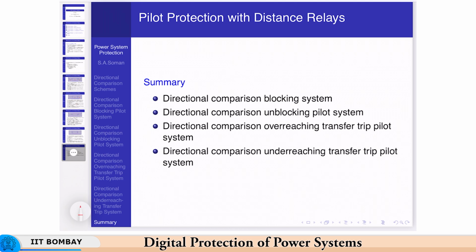another important topic, rather not a part of distance relaying. This is a feature which affects distance relaying, and that is how a distance relay sees a power swing. One reason why we discussed pilot protection before power swings is that though the pilot wire schemes will speed up the distance relaying decision, it will still not cover some faults that are there with distance relaying.